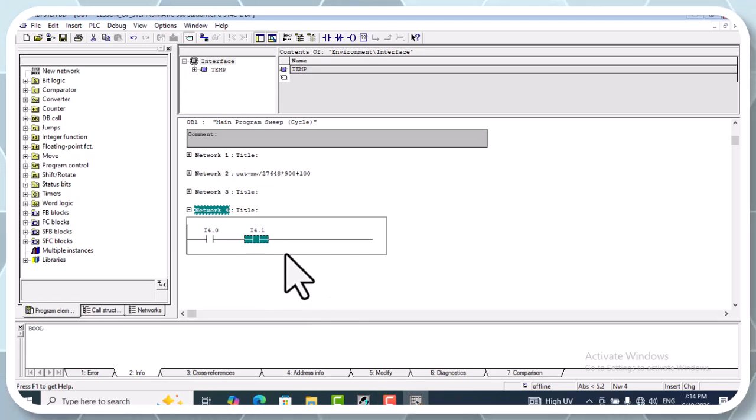And what we have here, my friends, is that in the future when you develop a program for a PLC, you will see that the absolute address does not look informative. So to make it more informative, you must use a symbolic name for your inputs.